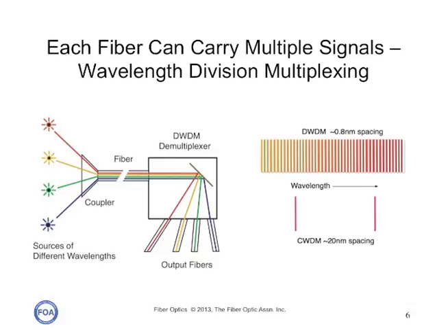And then on every one of those single mode optical fibers, we can put signals at different wavelengths of light, up to 128 different wavelengths today over one optical fiber, which means we're not talking about a terabit per second, we're talking about more than 100 terabits per second. And that's why fiber is used for every kind of communication you can imagine. And by the way, the term you learn here is wavelength division multiplexing.